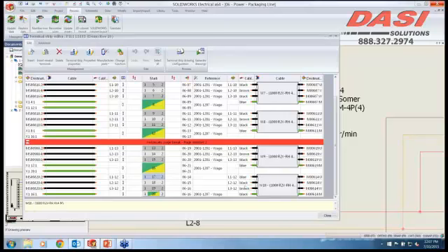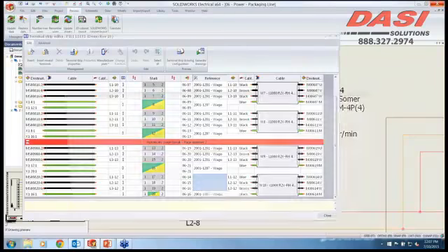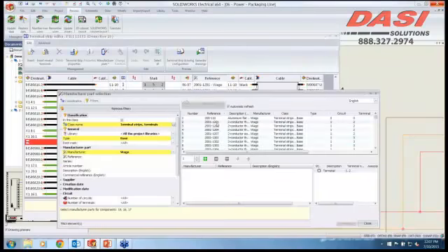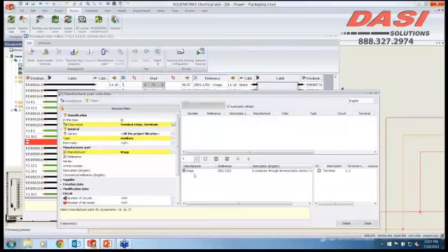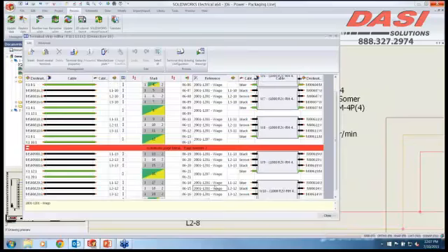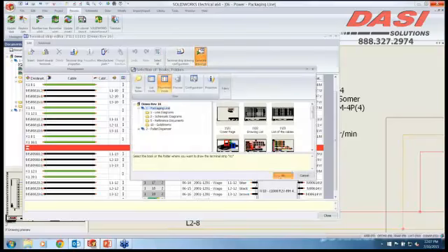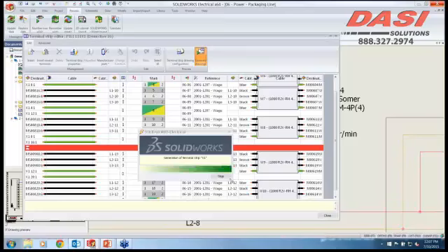I'm coming through this cable going through to the motor. Even assigning parts is as quick as grabbing an assigned part. Here I can grab this Wago terminal, and when I assign that in, it actually drops all that information in. I can then do another one-button click and get a terminal drawing.